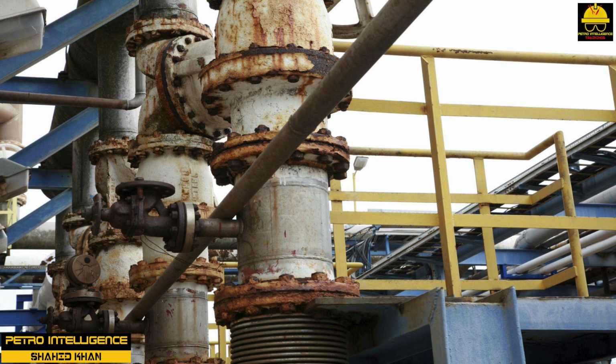A gasket should cover the entire face of the flange. Raised face flanges use a gasket that fits inside the bolts, and ring joint flanges use only a metal ring for gasketing. Flanges are made in various thicknesses and for various bolt sizes according to the pressure and temperature of the service. Ratings of 150 pounds, 300 pounds, and 600 pounds are common in chemical plants.